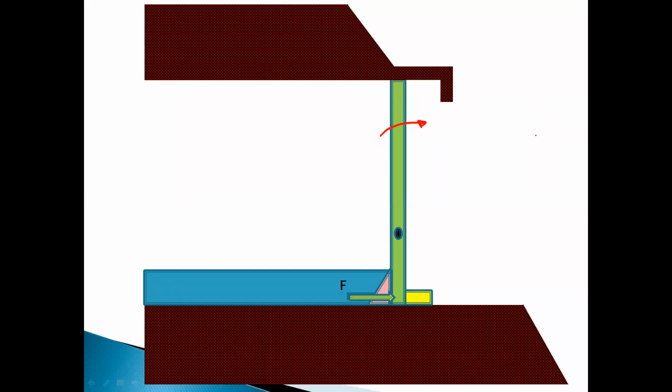So water pressure, suppose we have the wall. Okay. And on the left side of the wall, we have the water or any other liquid. Okay. So liquid pressure varies across the depth, and it varies like this, which is the uniformly varying load.